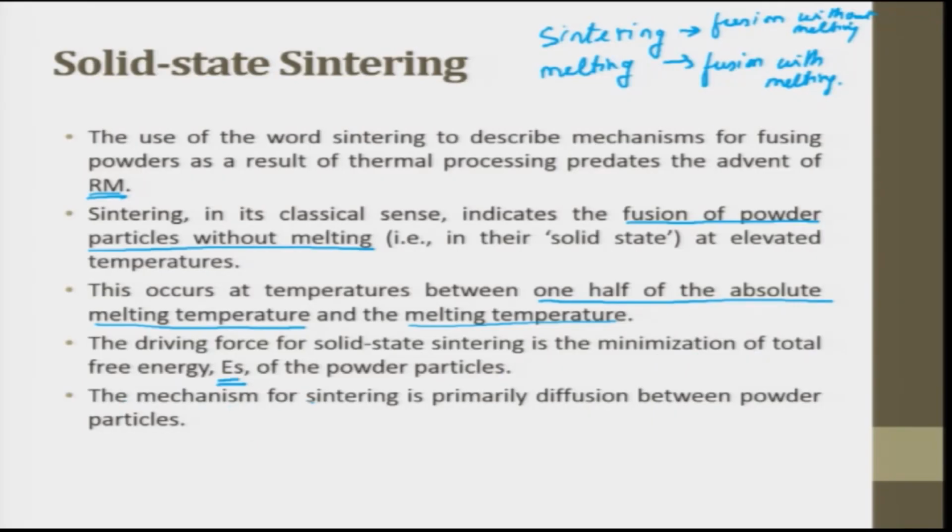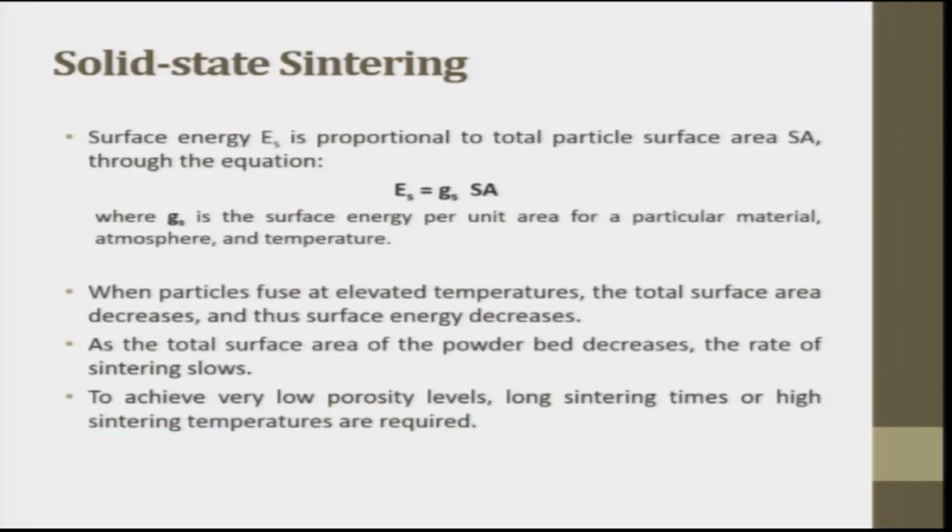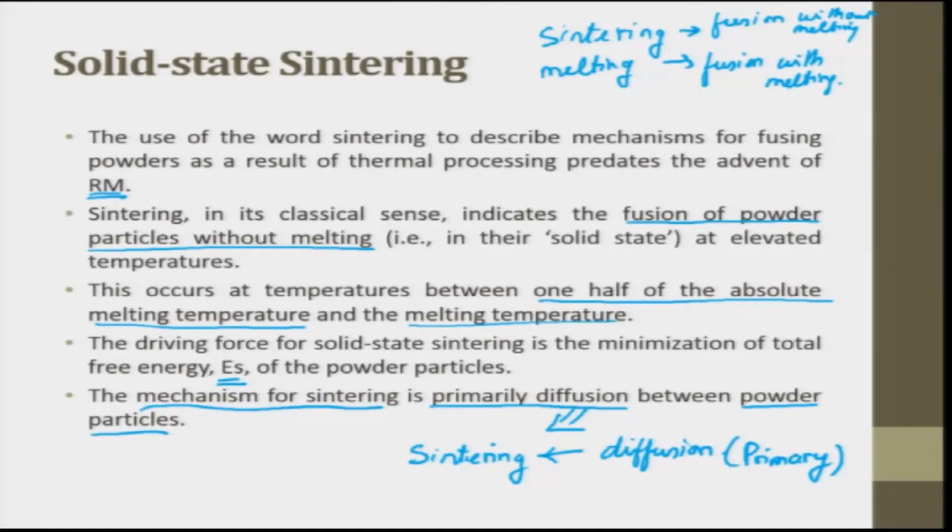The mechanism for sintering is primarily diffusion between powder particles. So, this is very, very important. Sintering process, the primary mechanism is diffusion. You have many more, but this is the primary mechanism.